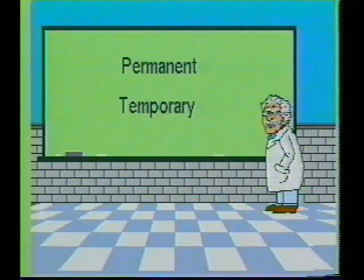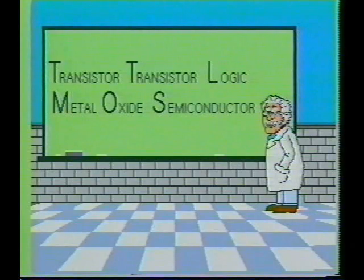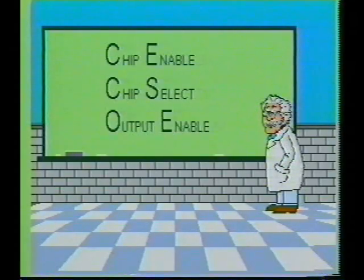There are two basic types of memory devices, permanent and temporary. The ROM is a permanent type memory storage device. Read-only memory devices are commonly available in both TTL and MOS configurations. The chip enable input is oftentimes referred to as a chip select or output enable input.